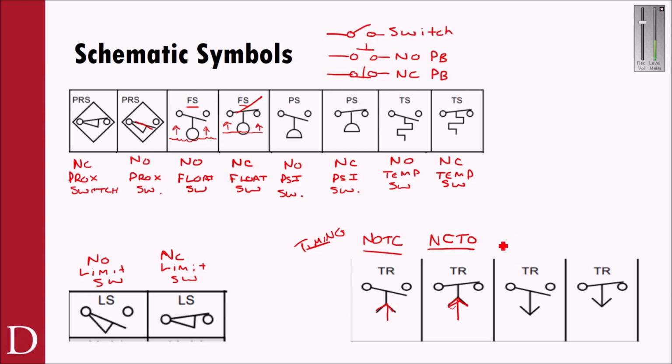This one here is normally open, time to open. So it's drawn as normally open, but look at the direction that this is going. It's going in the opening direction. So the idea here is I would energize a coil, this thing would close, and then it would delay to open after it was closed. Versus this one here, I would energize the coil, and it would not close right away. It would delay to close. So kind of an opposite action, but they're both drawn normally open.